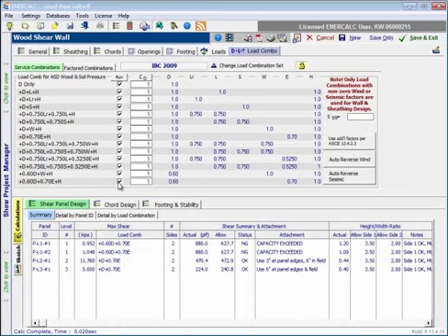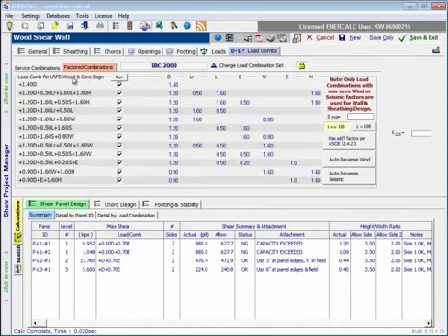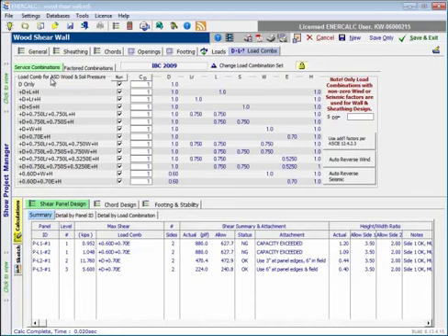For the footing, we are looking at all the different load combinations that are selected to run. So you may just choose to keep everything selected so that you can get a full look at soil bearing pressures and a full look at reinforced concrete design from those load combinations. But just keep in mind that the shear panels, the sheathing, and the chords are only being evaluated for the load combinations that include either wind or seismic.